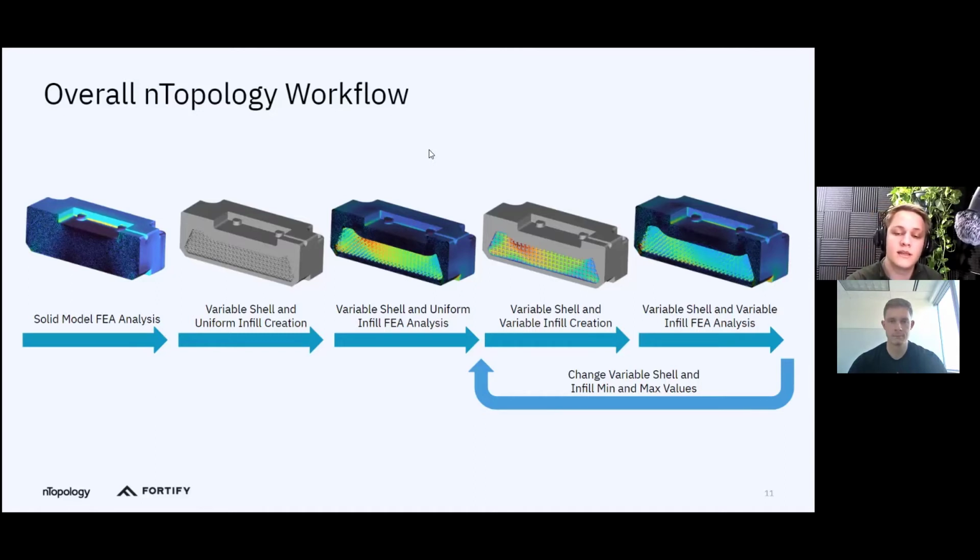And the reason I'm doing this is I want the stress in the actual beams of the lattice structure. So instead of taking the stress analysis from the solid mold, I actually infill it and then take the stress in the beams themselves. So it's a little bit more of an accurate way to do this field-driven design. You can see we do have a stress concentration area here in our mold inside of the lattice structure itself.